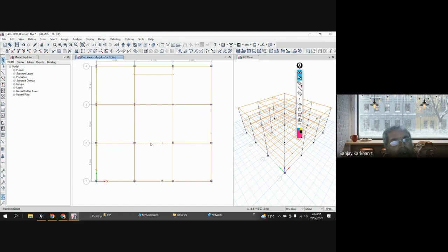Now if I click on this, this joint also I can delete. So I will delete this joint. But if I select this, as this joint is joined by two frames, and I do delete, it is not getting deleted. Why? Because if you delete the joint, how will this beam have the connection, because this is not one beam, these are two beams.